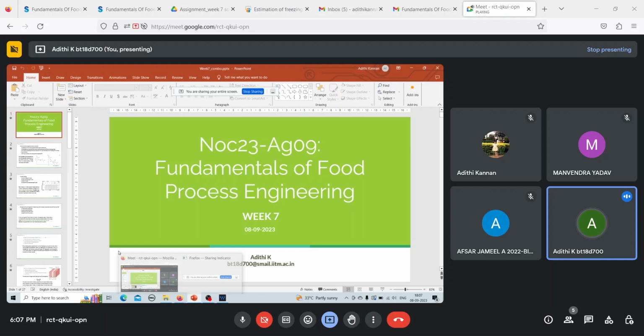Plus you have Cpf, which is 1.8 kilojoule per kg Kelvin, again multiplied by 1000 to convert it into joules, and this is times (Tfm minus Tc). This is just substitution. As long as you remember the formula, it is just basic substitution, no other calculation. Delta H2 comes out to be 2.5 into 10 power 8 joules.